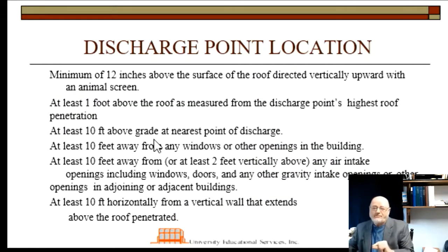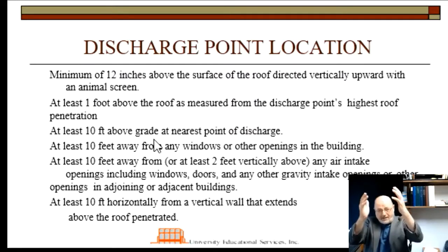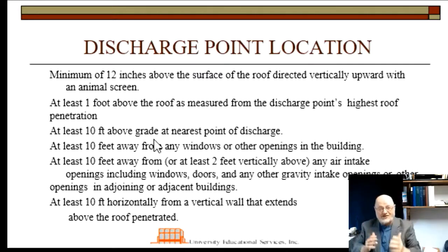The discharge point. I wanted to make a couple of remarks on this because remember that the soil gas radon concentrations can be in the hundreds and in the thousands. So you're going to be venting this gas up and out through an exhaust pipe, in effect. And it's going to come out of that exhaust pipe with concentrations in the hundreds and thousands typically. So you don't want to have that exhaust pipe coming out right near somebody's window, obviously, because a lot of that radon could easily get blown back in to the building. That typically is called re-entrainment. But you want to avoid that.